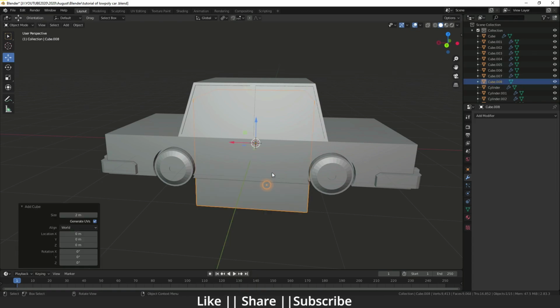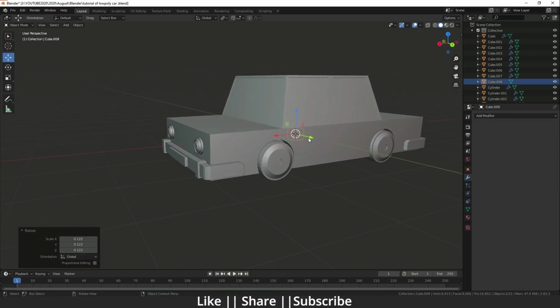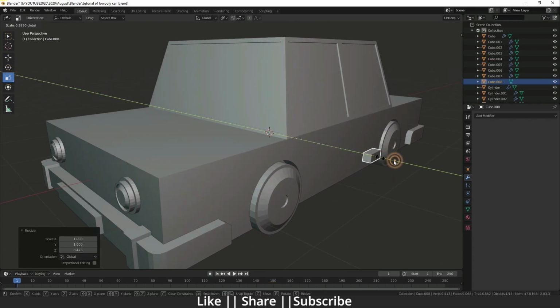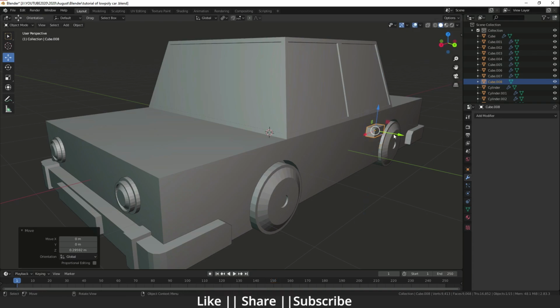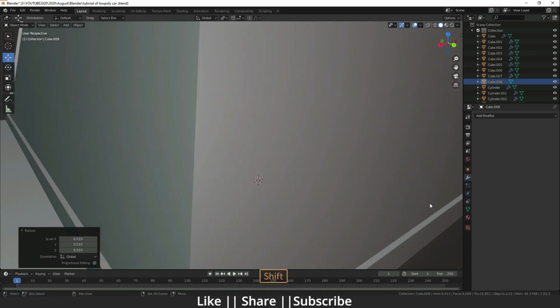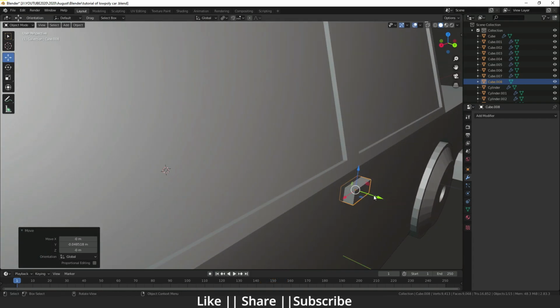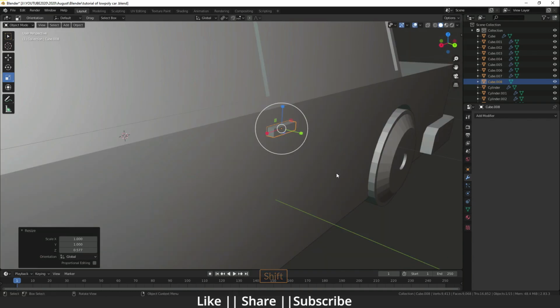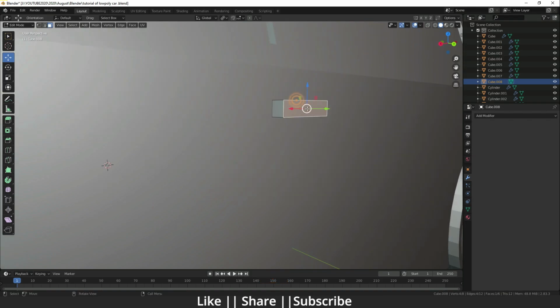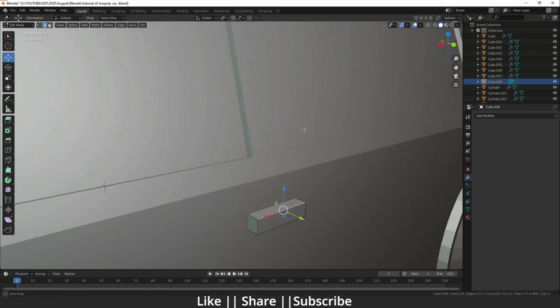So now I'm just going to make a handle. For that I'm just going to take one cube and do like that, and I'm just keeping it here and scaling it a little bit again, and doing like that. Then I'm going to the edit mode and selecting that edge, and if you do the bevel, it's a perfect bevel like that.